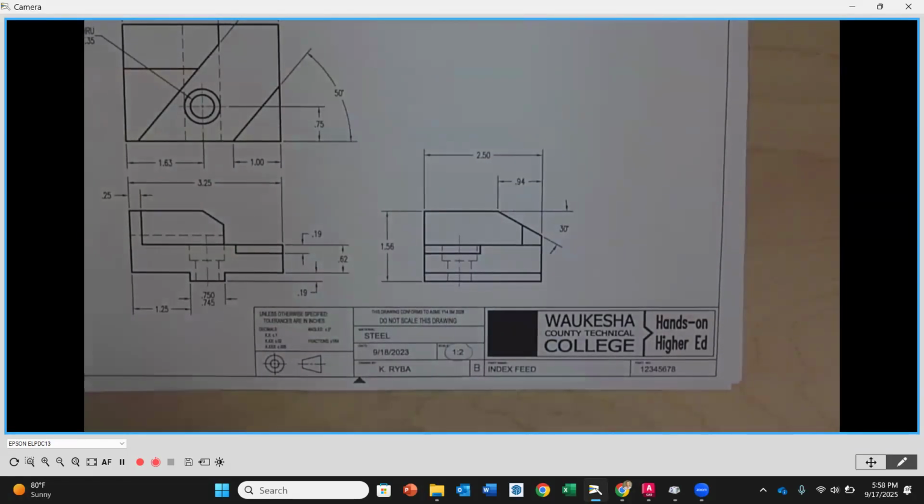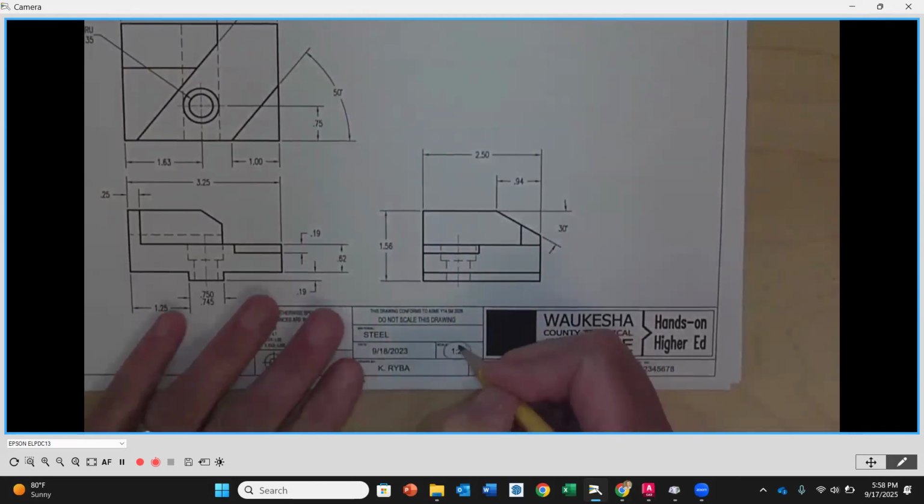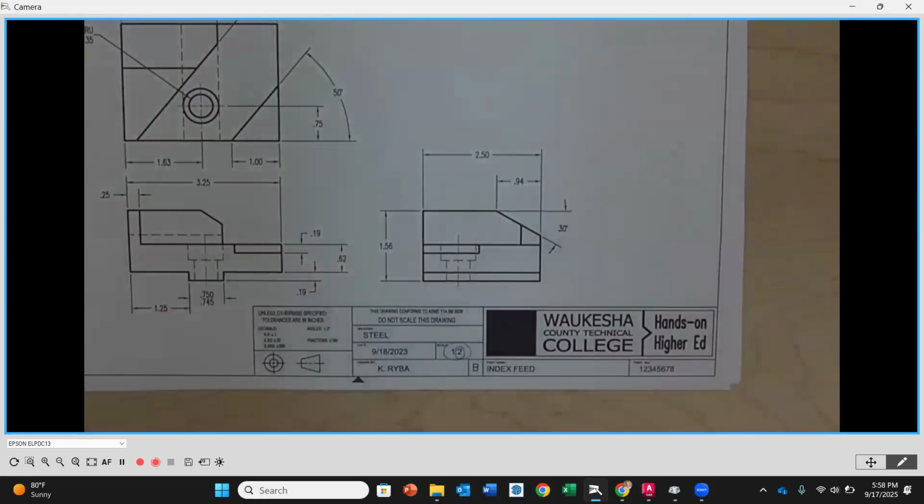What that means is I pulled this border in and I had to make it 2 times larger to fit around this drawing that was drawn 1:1, okay? So 2 is going to be the scale that we actually pull the drawing in at, okay? It's also going to be the scale that we're going to change in our dimension manager to then make the text the right size, so that we don't have to mess around with it too much, okay?